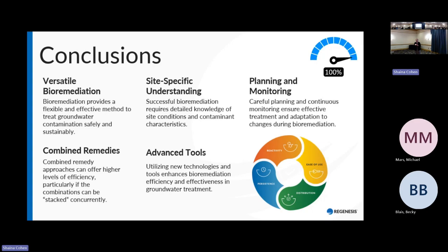And I think something that, I know this wasn't really your question, but just kind of wanted to point out to you, when we're talking about above ground systems where we're using GAC or something versus below ground systems, we're talking about such a different residence time, right? If we're thinking about what would be equivalent bed contact time for an in situ PRB versus an ex situ system, it's so different, right?